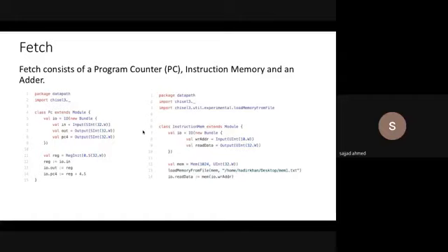If we look into the syntax of Chisel, if you are familiar with object-oriented languages, there is a class PC which extends Module. Module in Chisel is basically the parent class of every class you declare as hardware, and in it you declare your logic. Then we know that hardware has many IOs for input and output. There is a predefined function IO which uses the class Bundle to declare the IOs of your module.